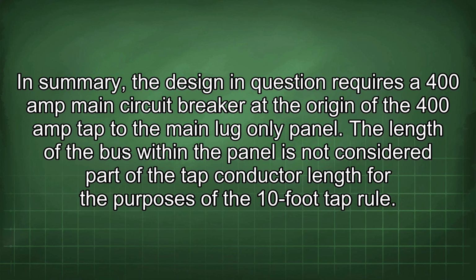In summary, the design in question requires a 400 amp main circuit breaker at the origin of the 400 amp tap to the main lug-only panel. The length of the bus within the panel is not considered part of the tap conductor length for the purposes of the 10-foot tap rule.